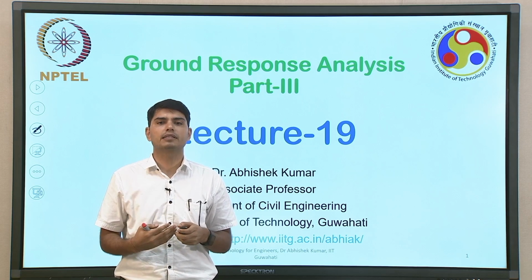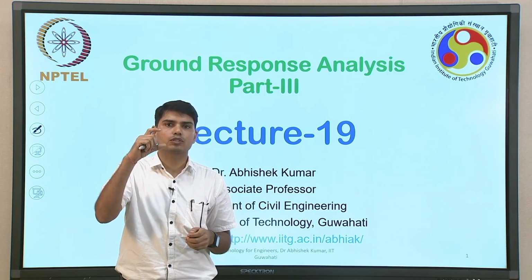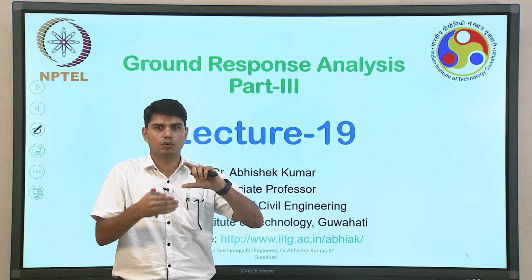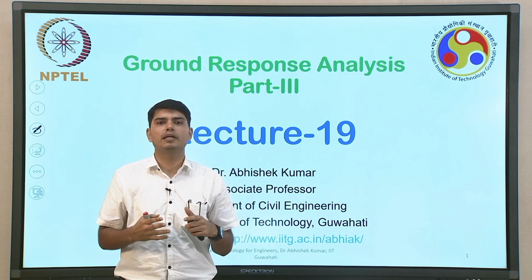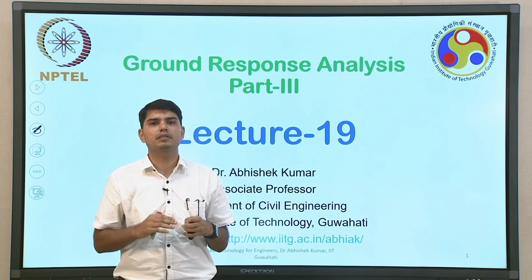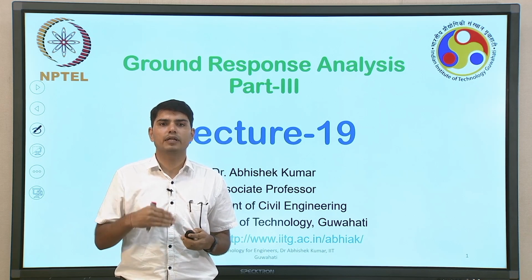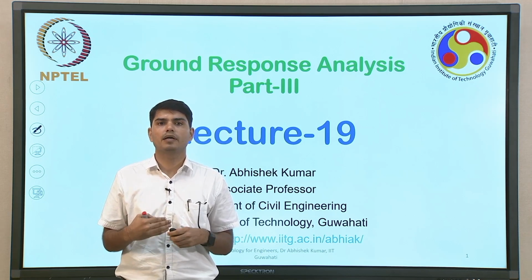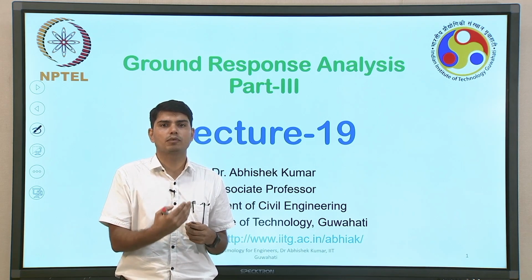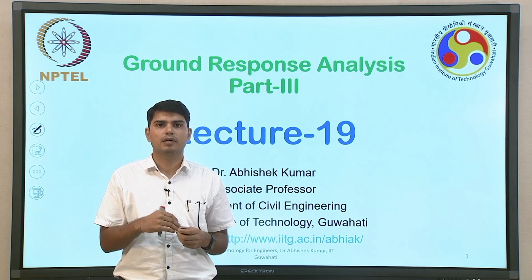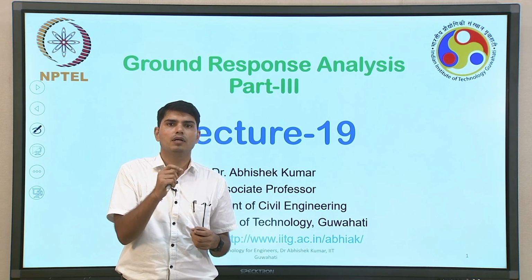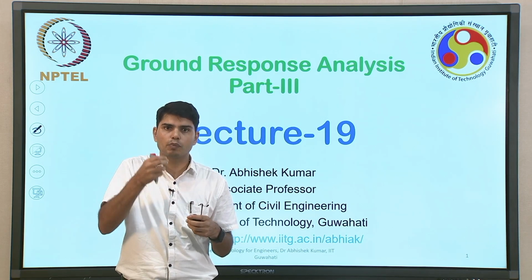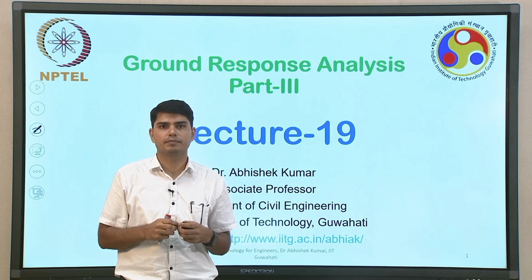In lecture 18, we discussed that the soil layer, for which we are interested to find out how much it is going to modify the motion, was basically undamped. Undamped means that there is no damping or no resistance offered by damping. So, solely the soil response is governed by how much shear modulus the soil has, which will control how the displacement values change as the wave propagates through the particular soil layer.